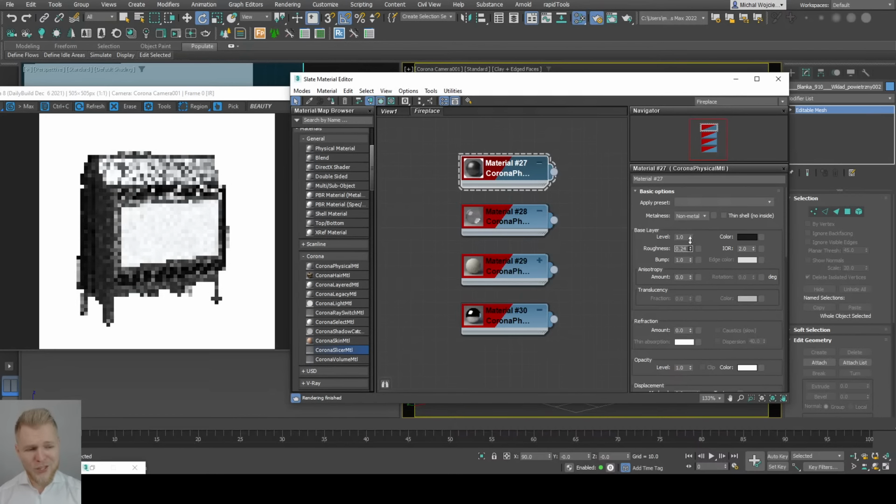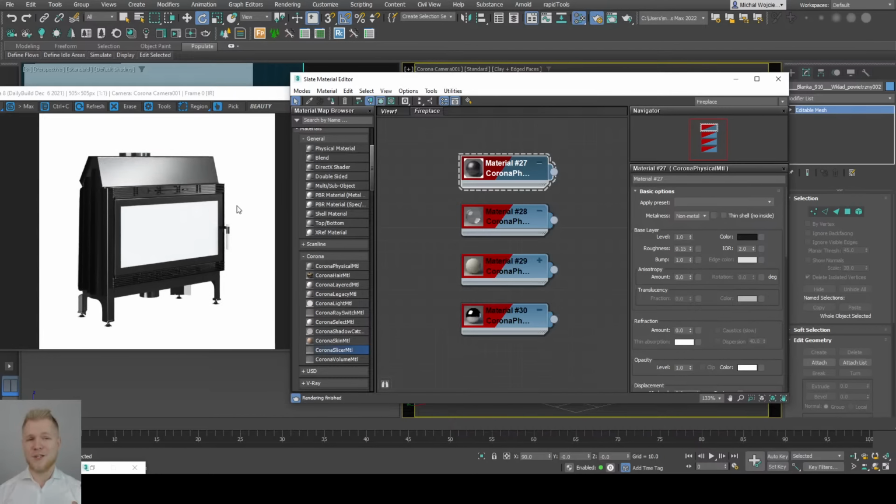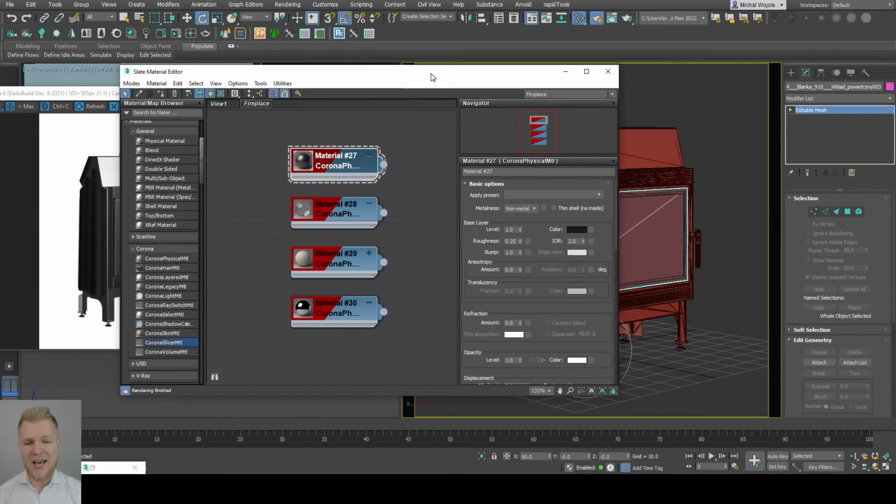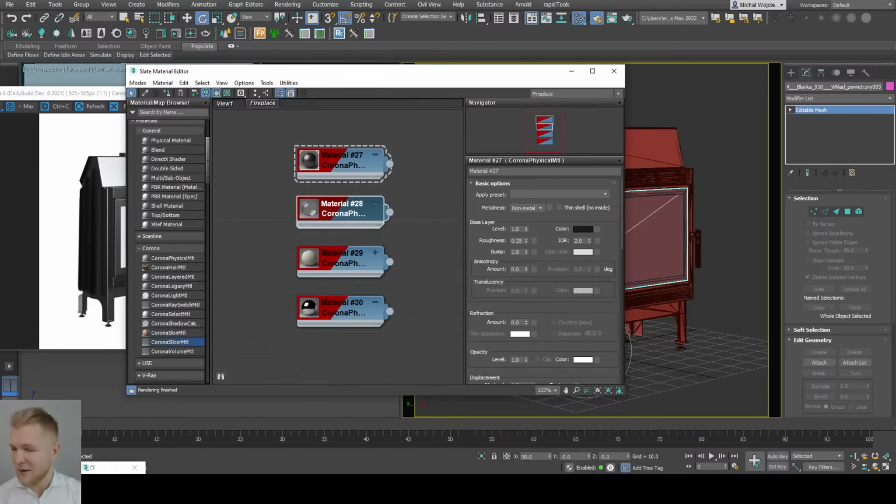So one tip that I can give you at the very beginning, if you're going to be working with objects that will be, let's say, carrying a little bit of glossiness, my tip is to use lower resolution HDRIs, because in that case it's going to save you a ton of time loading the scene, and basically it's going to just handle a little bit better.